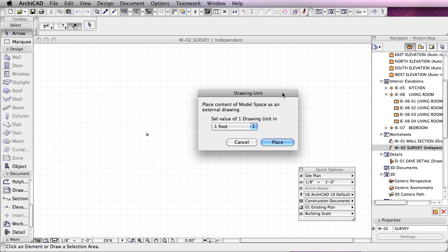Now, what you've got to understand is that in DWG files, the elements are described based on how many units in length or placement they are. So in other words, something that's 100 units in length, a line, could be 100 feet, 100 meters, 100 miles, anything. So we need to choose what that's going to be.